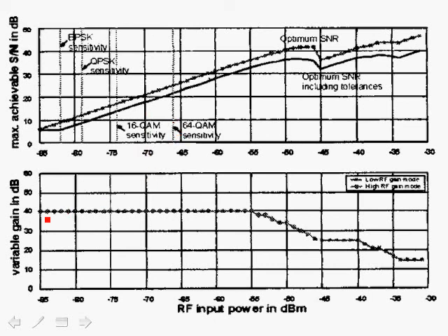So in this diagram, initially throughout the high gain setting, the receiver is set to the highest gain and we have a low signal to noise ratio, low input power. The signal to noise ratio increases as the signal power increases. However, the gain is constant, but as the signal to noise ratio starts to increase beyond a certain point, we have to start peeling off the gain in order to avoid saturation and meet our target RMS value. In this case, the RF variable gain kicks in and we reduce the RF front end gain, and then we start adjusting the baseband variable gain amplifiers in order to meet our target RMS at the output of the A to D, or consequently at the input of the A to D.